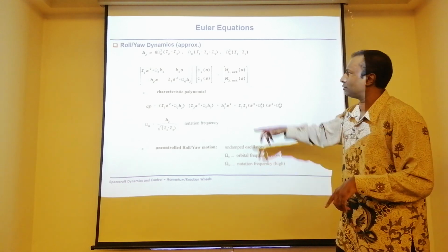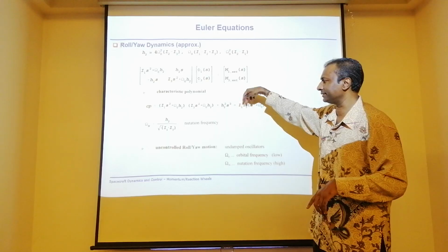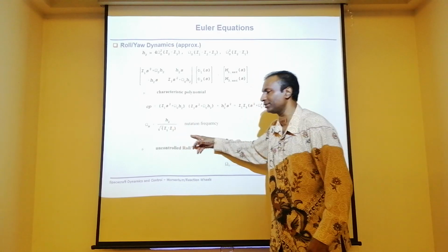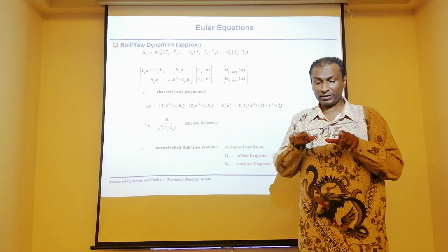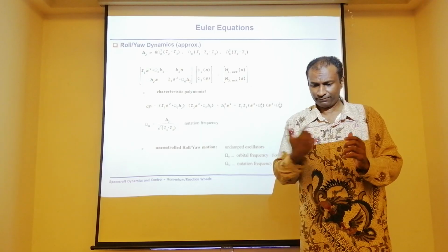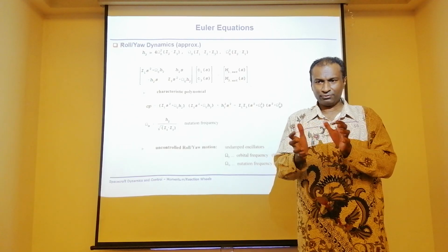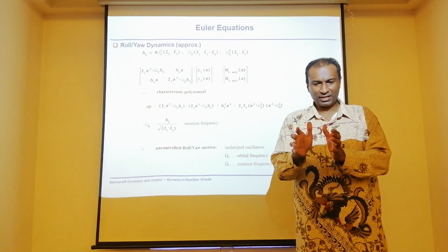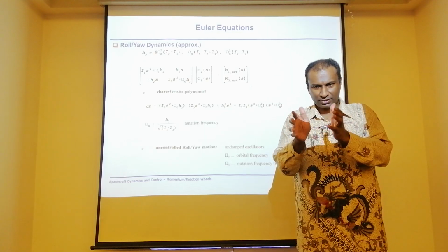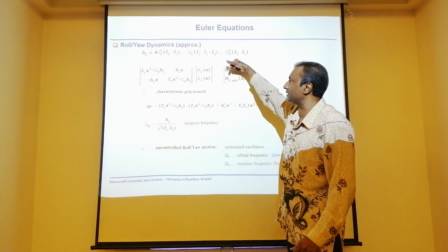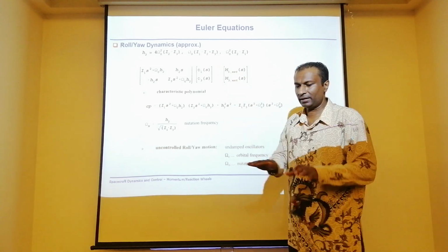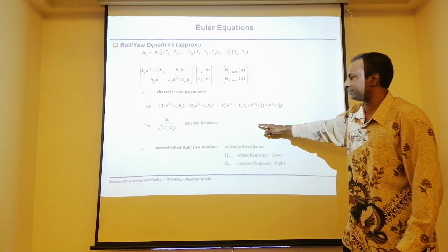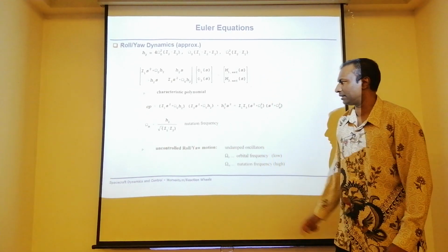Okay, gyroscopic stiffness. So when we do an analysis, it seems that it produces slightly a nutation. There is some nutation frequency. Why is there a nutation frequency? Because when you produce a stiffness, this is stiff. If you throw a top spinning at high speed, you can see it is not just stiff like that. It may produce a wobble like this. So that means the two other axes, roll and yaw, might also have a bit of nutation. Okay? So the nutation frequency can be calculated.